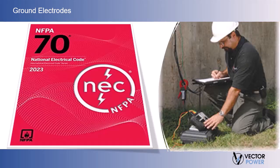The National Electric Code, NEC, states that the resistance to ground shall not exceed 25 ohms. This is an upper limit and guideline, since much lower resistance is often required. How low should a ground be? An arbitrary answer in ohms is difficult. The lower the ground resistance, the safer, and for positive protection of personnel and equipment, it is worth the effort to aim for less than 1 ohm.